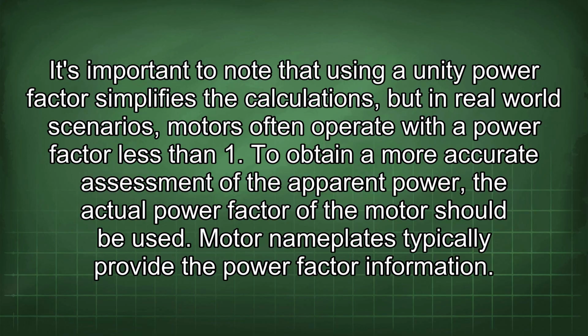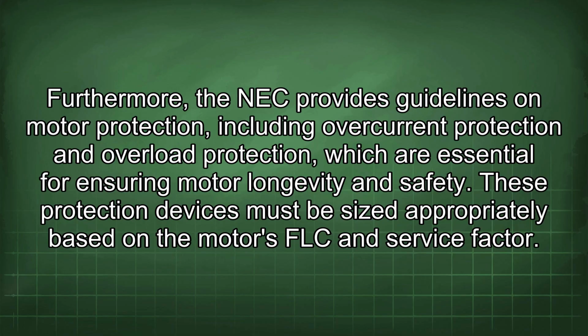To obtain a more accurate assessment of the apparent power, the actual power factor of the motor should be used. Motor nameplates typically provide the power factor information. Furthermore, the NEC provides guidelines on motor protection, including overcurrent protection and overload protection, which are essential for ensuring motor longevity and safety. These protection devices must be sized appropriately based on the motor's FLC and service factor.